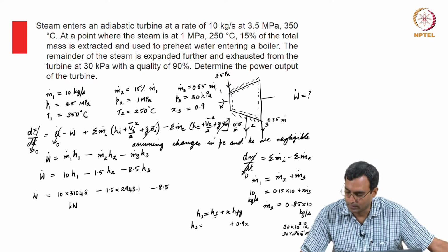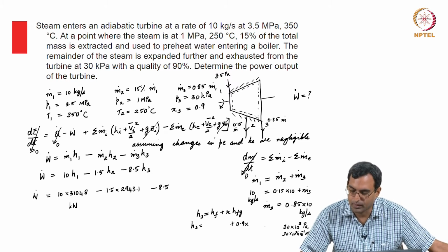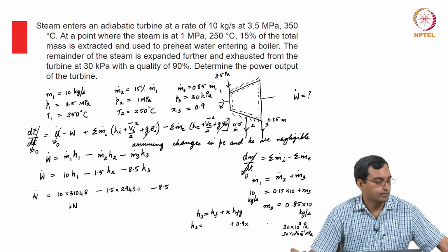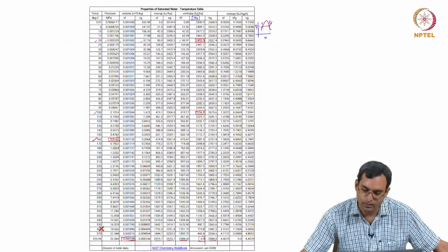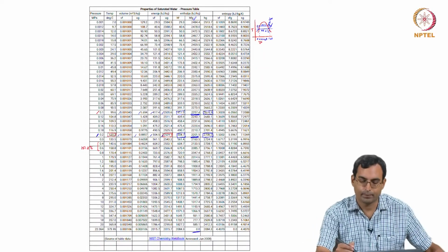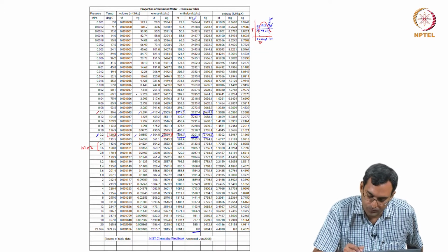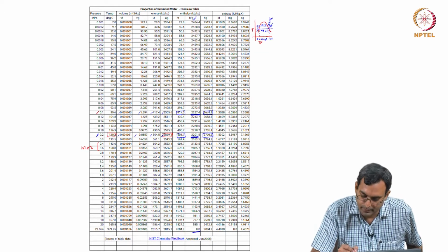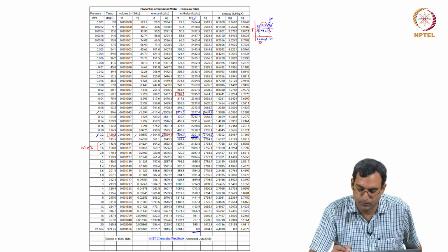So, I have minus 3, which is essentially 0.03 megapascal. I need these values at 0.03 megapascal from the saturation table. So, let me look at the things listed by pressure. At 0.03 megapascal, what I need are HF, which is 289.3, and HFG, which is 2335.2.